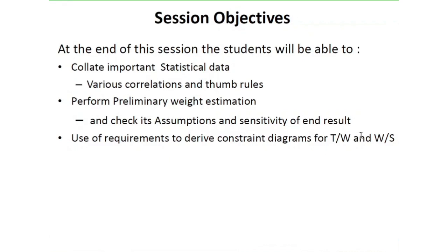However, in a combat aircraft, fuel consumption rate or the economy of fuel consumption is not the primary criterion. If it is good, it is acceptable, but what is important is the functionality. If the aircraft has to do an 18 degrees per second sustained turn rate, it has to do that. Doesn't matter. If for that you need a very low wing loading and a very high thrust loading, so be it. So that depends on the kind of aircraft you are designing.